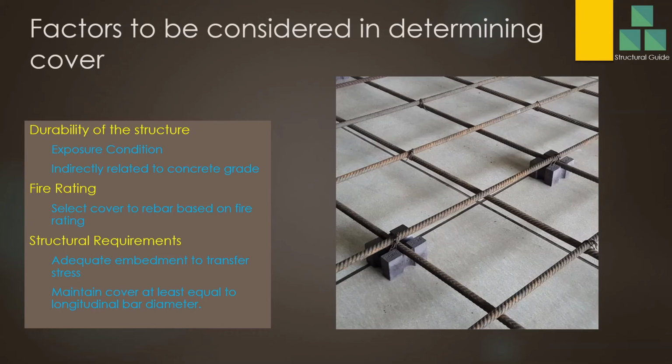Next is the fire rating. As I discussed previously, depending on the fire rating, we have to select the cover. How many hours do we want the structure to last without damage? That is there because we need to safely evacuate the people from the structure if there is a fire. Then the structural requirement we have to consider.